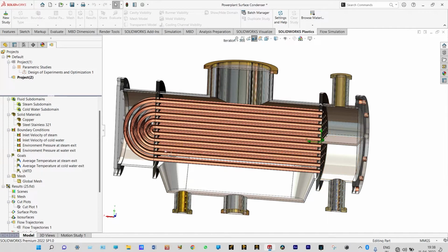It will pass through these tubes and finally it will come out from this top exit in the form of a bent U-tube. And as we are providing hot steam from the top side, there will not be any kind of direct mixing of hot steam and cold water. By convection, steam will lose heat, and at the bottom side we will have steam condensate.